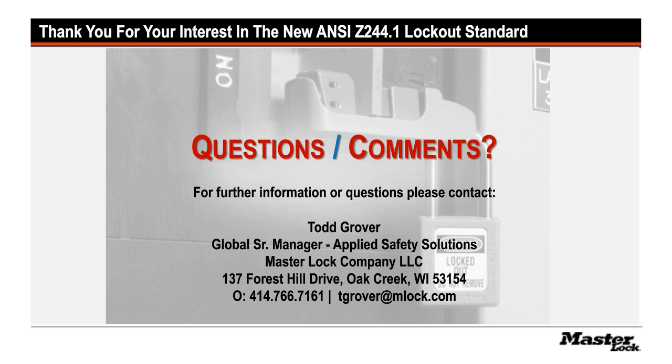It should also be done under the eyes of people who have explicit experience with the operations of the machinery being assessed. So we find that often risk assessment is multidisciplinary. We would expect that a safety professional would be involved in a risk assessment, perhaps along with the operator or the maintenance mechanic that is familiar with the task and the work to be done. There may be an objective set of eyes, such as a department management, plant engineering,